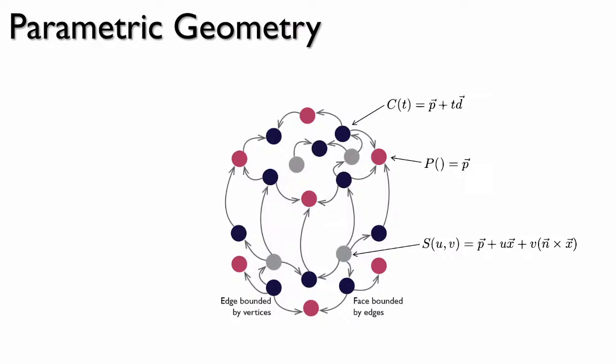The reason this is important, by the way, is that these parametric equations don't have boundaries by default. A plane goes on forever, so you need some of the topology to cut out the shapes you care about. This data structure we're looking at is called the parametric boundary representation, or PBREP. This is the lingua franca of the CAD world. Basically, any commercial CAD program you see is using this representation, and using it as a data exchange format.